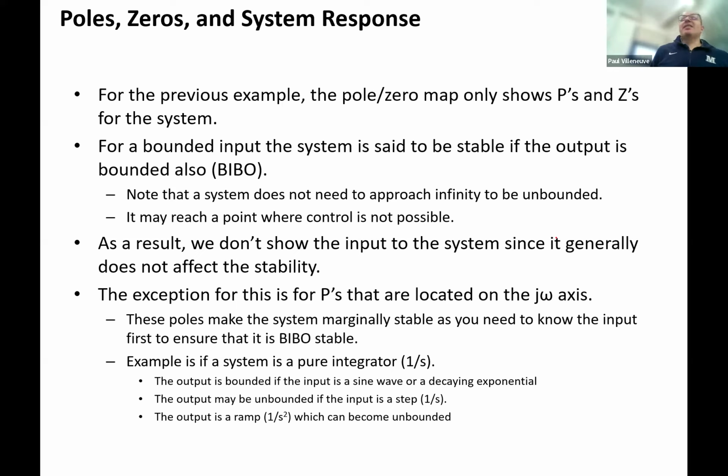The absolute best efficiency is going to be based on the temperatures, right? So the higher the temperature you can get, and the lower the temperature you can get, is your Carnot efficiency. That's like the theoretical maximum efficiency you can have. So if you think about from a control perspective, why do we want to run at superheat levels at really high temperatures? And why do we want to have our condenser? Because we want to condense our water at as low a temperature as possible so that we can maximize our Carnot efficiency.